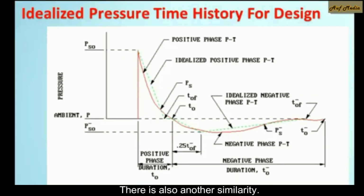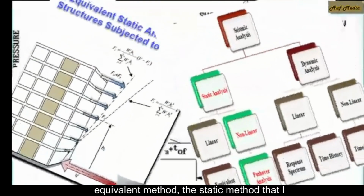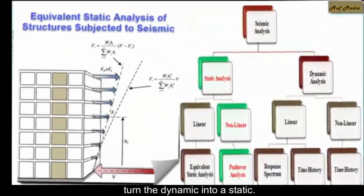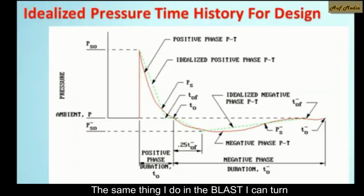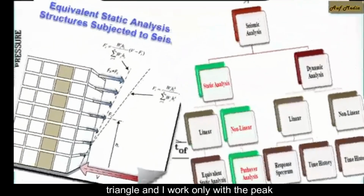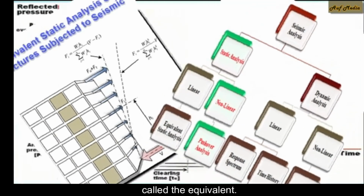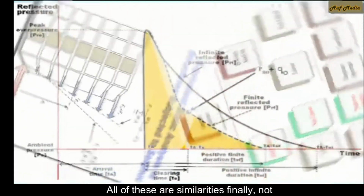There is also another similarity. The seismic, I used to solve it using the equivalent static method, where I turned the dynamic into a static. The same thing I do in the blast: I can turn the curve, which is the exponential curve, into a triangle, and I work only with the peak force or the peak pressure that comes from it. And I load the building with something called the equivalent load. All of these are similarities.